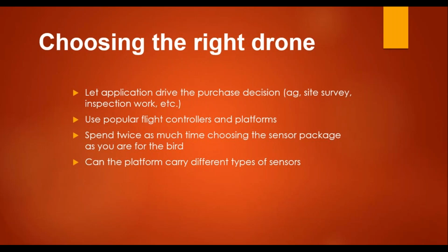There are a number of different types of payloads available nowadays for different purposes, different applications, and with different capabilities. UAV sensor payloads can include high definition video photography, a very common payload on UAVs, used for various purposes. Thermal imaging is also there, which is very important, especially in disasters and other applications, like an earthquake where humans are trapped in the rubble of a building. Thermal sensors on board the UAV can help to a large extent. It can also monitor radiation levels, because going into an area where radiation may be very high is dangerous for humans, but such a machine can be sent for the survey.